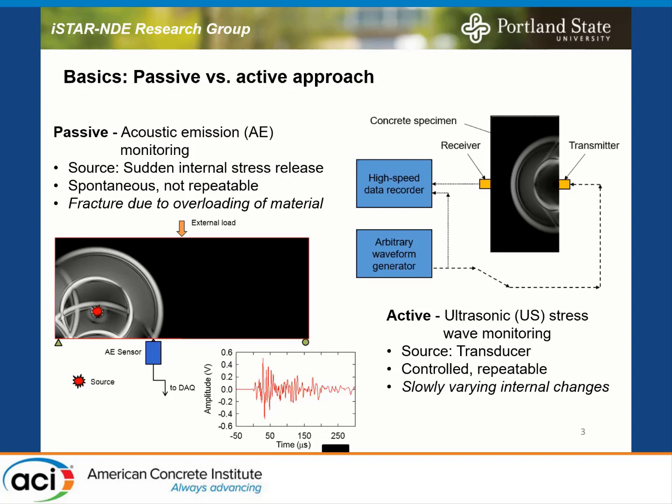That's very appealing, so we can capture internal fracture as it occurs. The problem is, initially, we have no clue where the source is. We don't know what the reason is. We don't know anything. We just pick up signals, waveforms at these locations on the transducer network, but we don't know where the source is. So it's spontaneous. We cannot really well control it, and so we can also not repeat it. Once such an energy is released, you can't do it again. It's released. So each acoustic emission is unique.